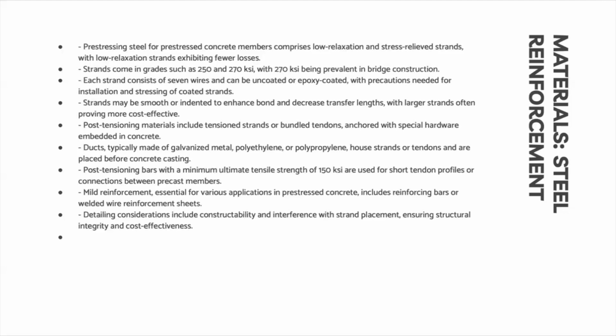constructability and interference with strand placement, with options ranging from lap splicing to welded wire reinforcement sheets as alternatives to reinforcing bars. Ultimately, careful consideration of detailing choices ensures both structural integrity and cost effectiveness in pre-stressed concrete construction.